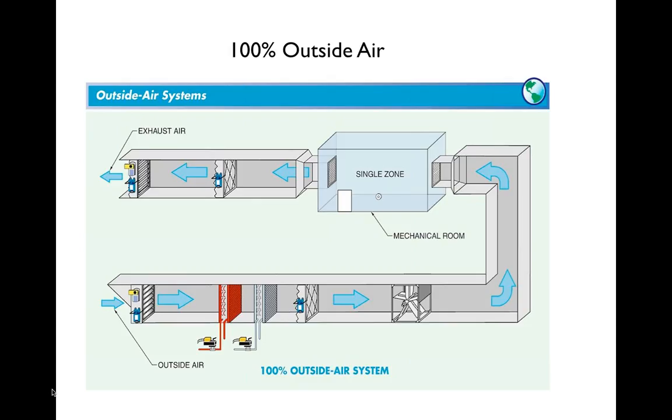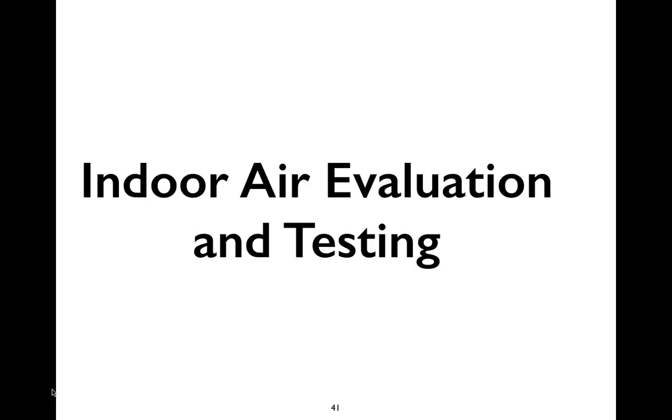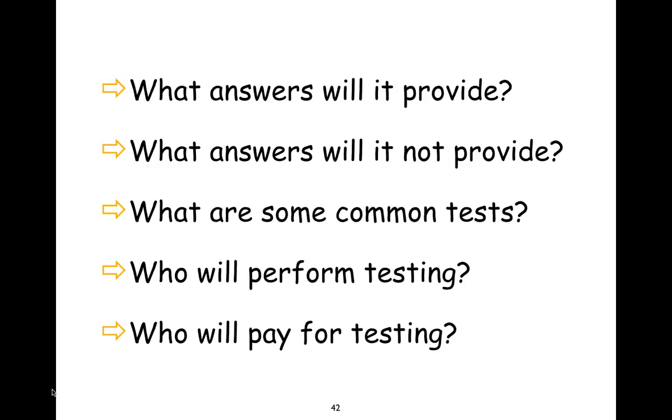In this system, 100% outside air is coming in. Actually, some hospital suites use this. Certain operating rooms use high efficiency filters, and they all use once-through air. Endoscopy suites and so on use 100% outside air. You can imagine the odors there, so you want to control those.